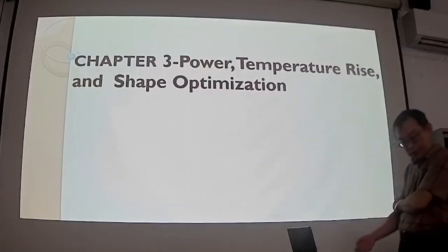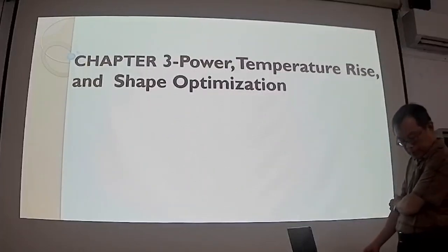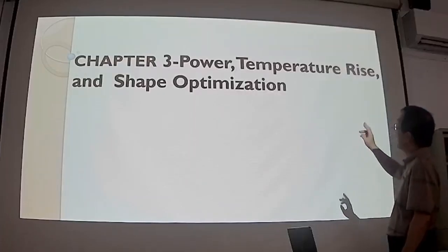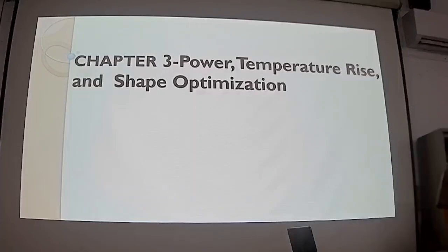For the next chapter, we will discuss the pumping power and also the temperature rise for the hydrostatic bearing. We are pumping the oil at high pressure under very small film gap thickness. So due to the viscous flow friction, you will generate a lot of heat in your lubricant. So you will have a temperature rise in your lubricant.